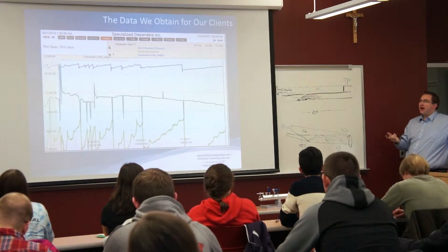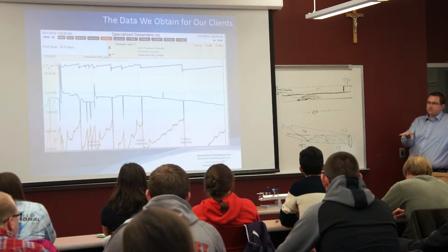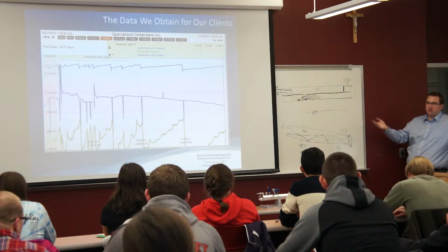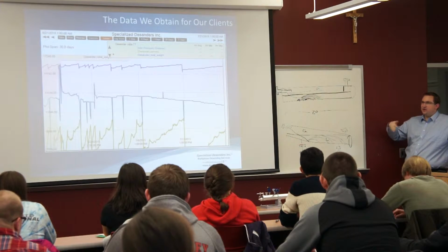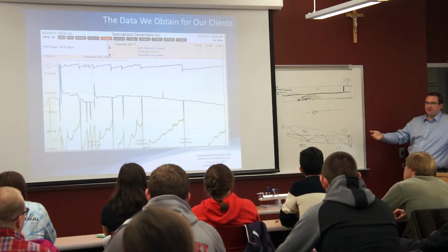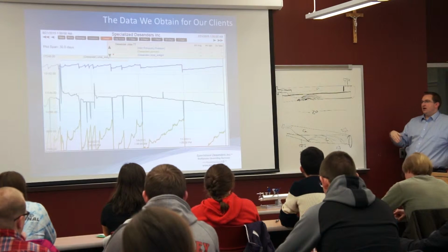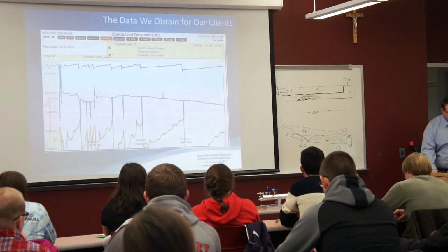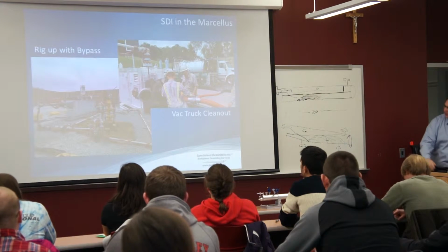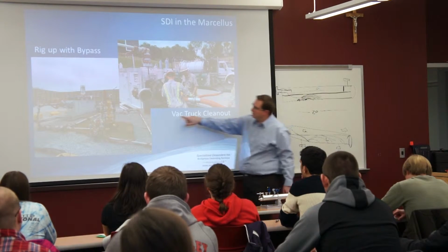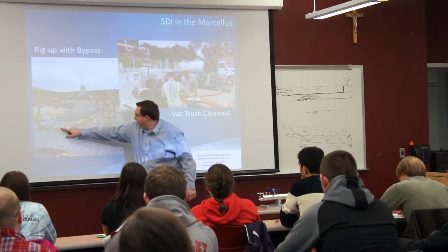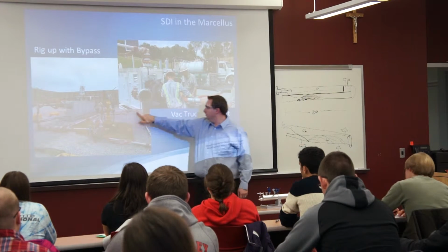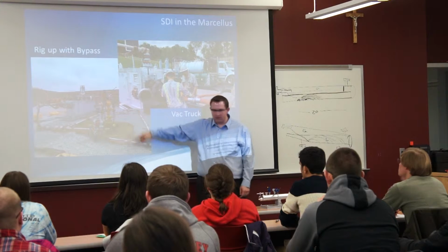So in cases where you do not want to shut in the well during the clean out, you can bypass through a different sand protection solution, one that might be less suited to extended periods of protecting yourself from sand. A Y strainer, so basically a screen put in a bypass line. That's what was going on up here. You see where it's bypassed. So when we would clean out the well, we would isolate it here, isolate it downstream, and then they just bypass through this line here and through a Y strainer.